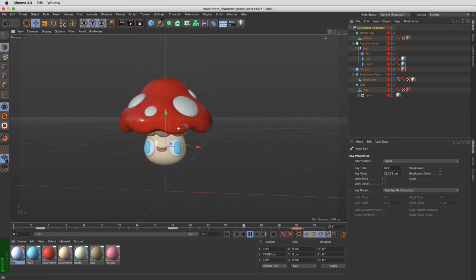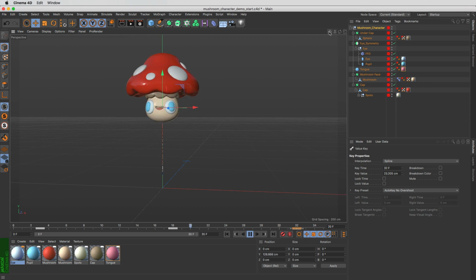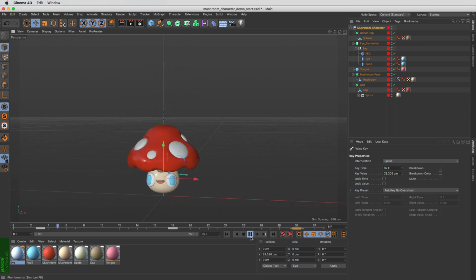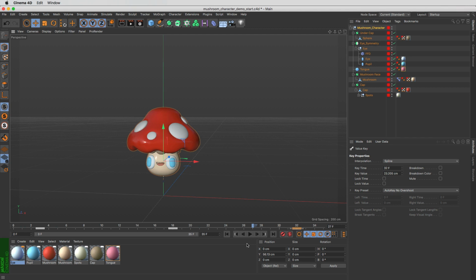And I'm just going to go ahead and use these little widgets in the top corner to reframe my animation here in the viewport. So I'm going to click the pause button, and what I want to do is add more character, inject more energy and interest into my animation using what's called a deformer. Now, a deformer is something that deforms geometry. It's very aptly named. And one of the animation principles that I absolutely love and love applying to my objects is squash and stretch. And there just so happens to be a squash and stretch deformer.